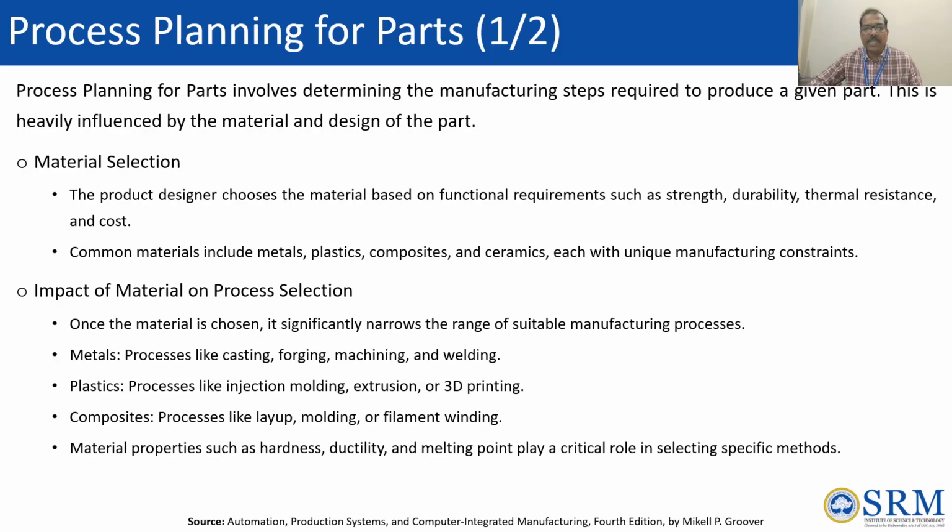Once we complete the rough turning, then we go for the threading. After doing the step turning, we need to do the threading and the chamfering, and after that we can do the knurling. If we keep knurling on one end, but on the other end we have done the thread cutting, then we can't hold it. So we have to do the knurling, then we can go for thread cutting. Likewise, which operation needs to be done first, that sequence we need to decide.